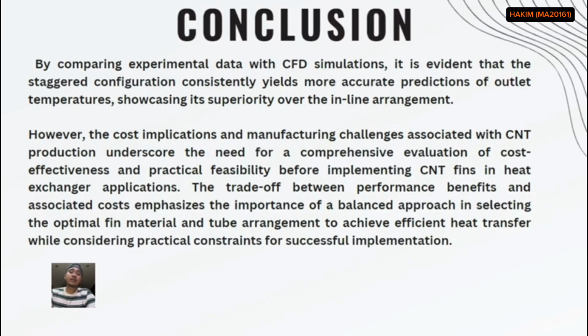By comparing experimental data with CFD simulation, it is evident that the staggered configuration consistently yields more accurate prediction of outlet temperature, showcasing its superiority over the inline arrangement. However, the cost implication and manufacturing challenge associated with CNT production underscore the need for a comprehensive evaluation of cost effectiveness and practical feasibility before implementing CNT fins in heat exchanger applications.